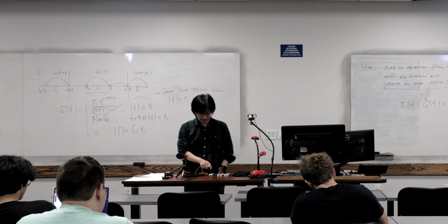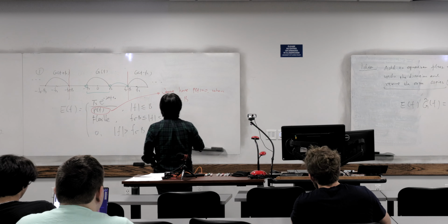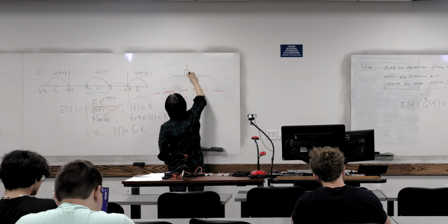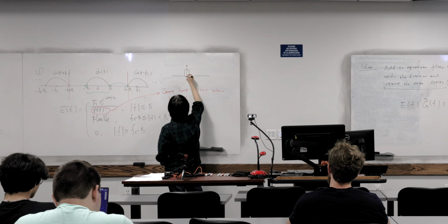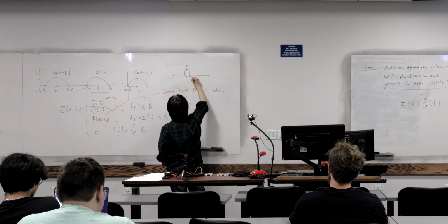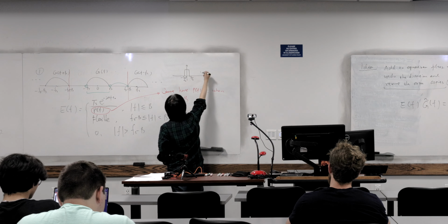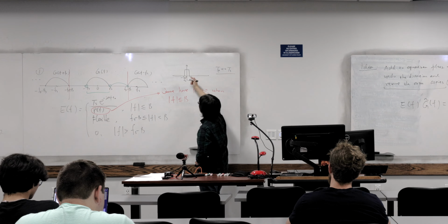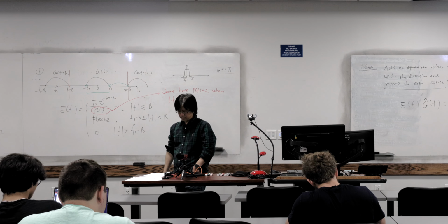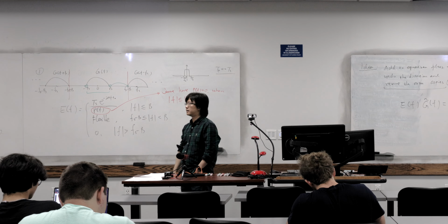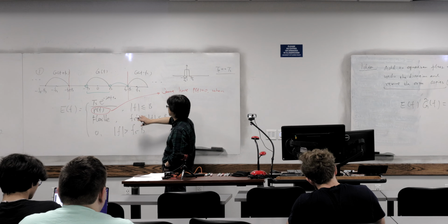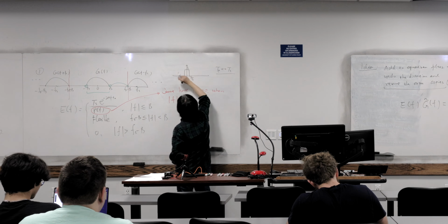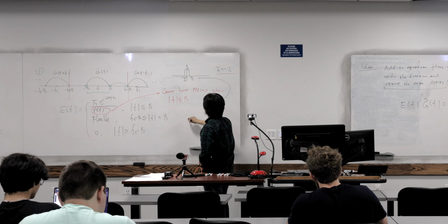For example, let's double check this kind of pulse shape, which supposedly should maybe be the best. I give you something causal, doesn't matter much. Let's assume this, we'll have TP over 2 minus TP over 2. And we assume the TP is much less than TS. In this case, it's a very narrow pulse shape. And in order to double check it, we need to check its frequency representation, PF. It's a rectangle pulse. Let's assume that is 1 here, okay? Then what is the frequency representation?